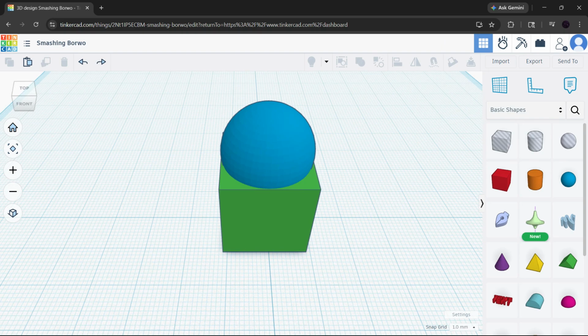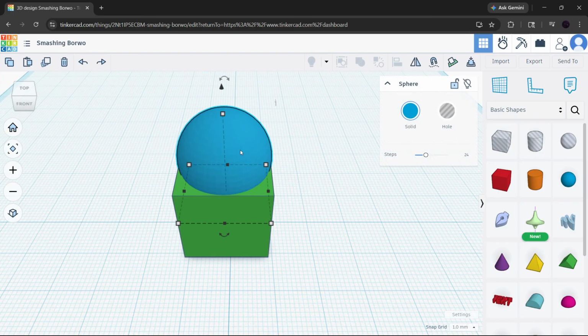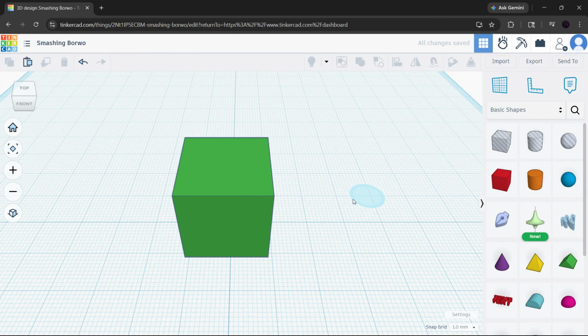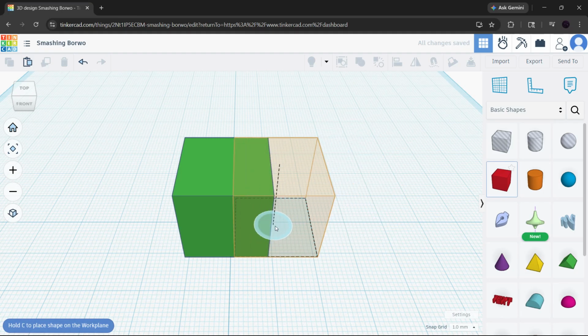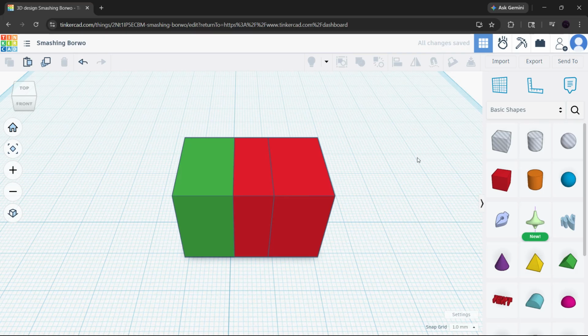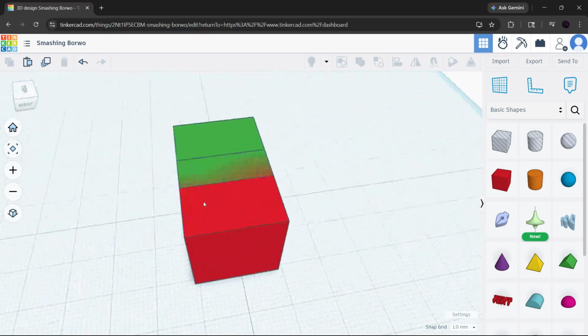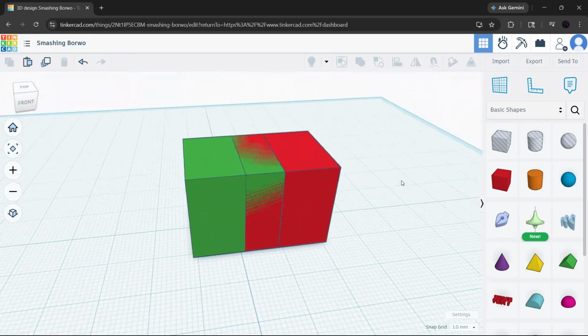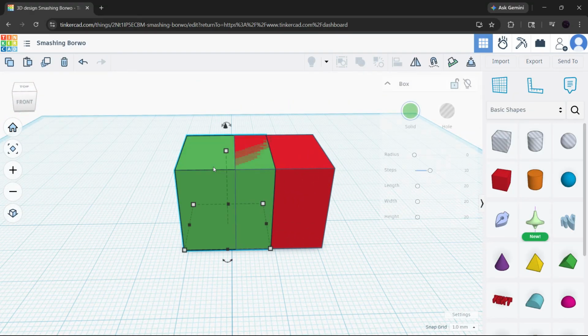One easy way to simulate this is to place two solid shapes so they overlap, then change one of them into a hole and group them. This will leave only the shared area or create a partial cut depending on how the shapes are arranged. Another option is to use the Intersect shape generator in the Shape Generators menu if available in your version or collection of shapes. This type of tool is designed to keep only the overlapping volume between objects. It's a great technique when you want more advanced custom geometry without needing complicated software.